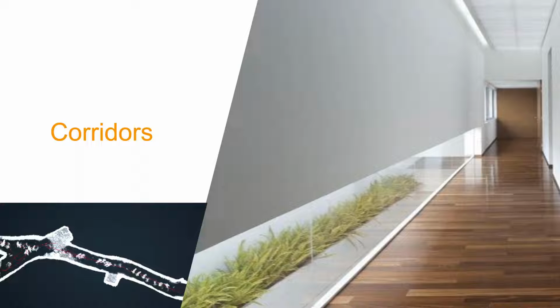The same applies for capturing tunnels. If you have any openings like this in the bottom of the cross section of the tunnel, on the bottom of the screen, you could make use of them and just make sure that you walk around them. This way you wouldn't be doing just a linear capture and you would allow to see any possible features in each direction as you turn around.